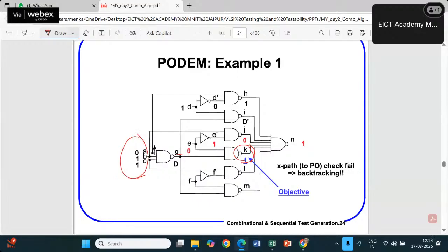Fault activation was, this is stuck at 1, so we have to make it 0, 1 and 1. 0, 1, 1 is the primary input set. For the system, there are 3 more and we have to find out their values, right? So what will be their values for those 3 that we have to cover, and covering that value is going to give us these results.